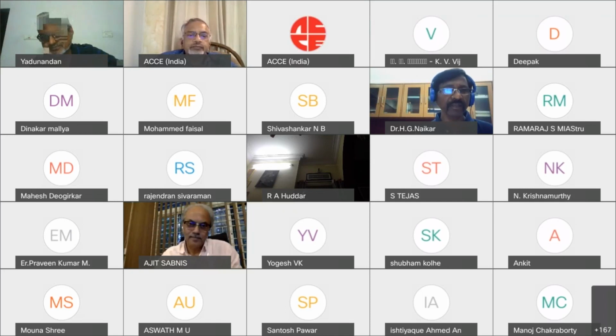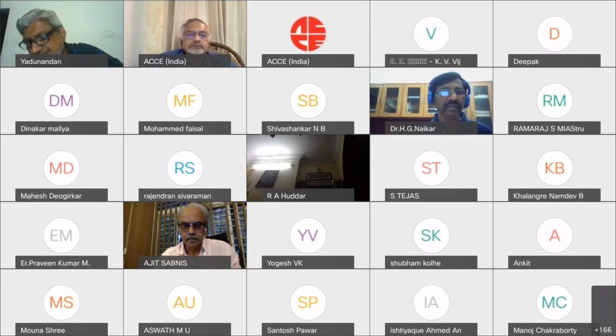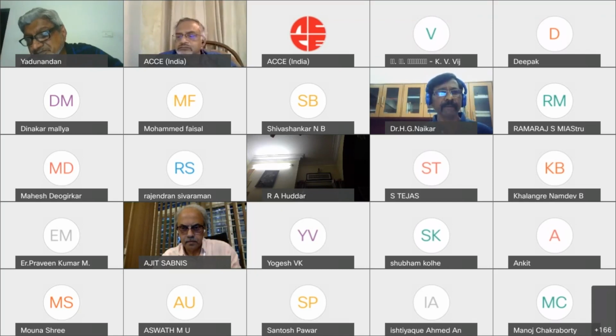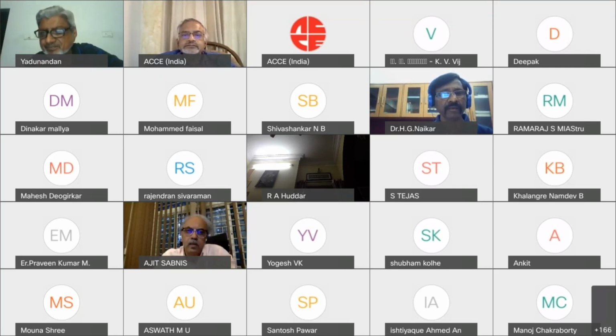I need another clarification. In case of footing, it is always economical to go in for a stepped footing. But when it comes to construction, there are challenges. So can you please elaborate how to go about it? Stepped footing cannot be cast at a time, so it will be cast in two stages. So if there is a gap of say more than 2 to 3 days, the column cannot be cast at a time, you continue with the vertical joints. No, sir, I'm not talking about the columns, sir. Stepped footing.